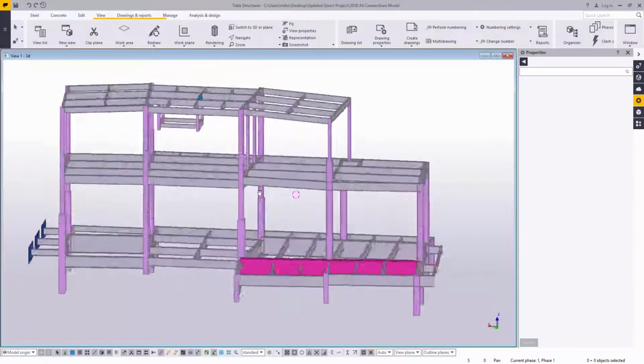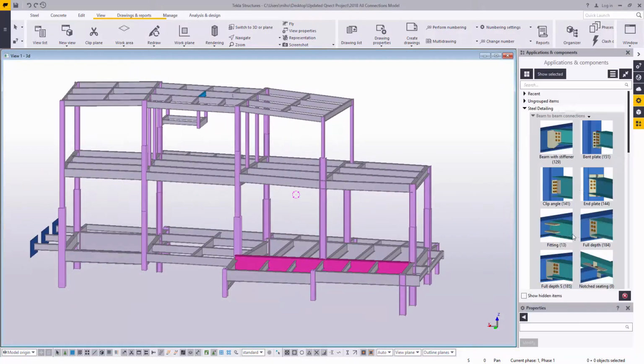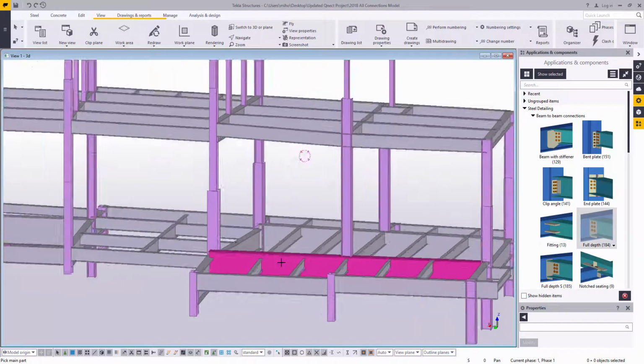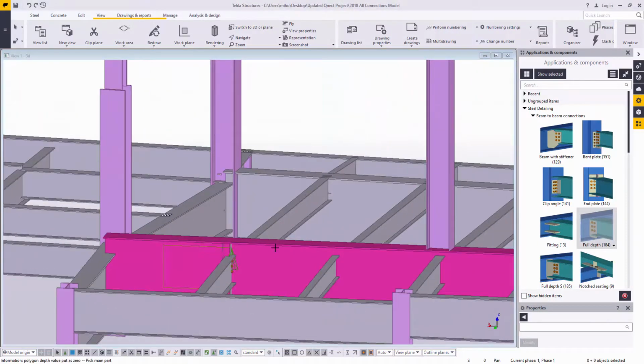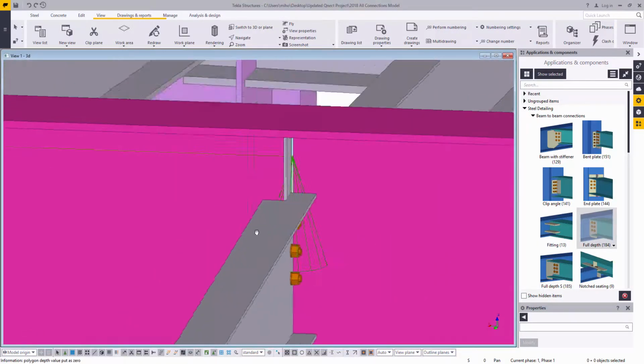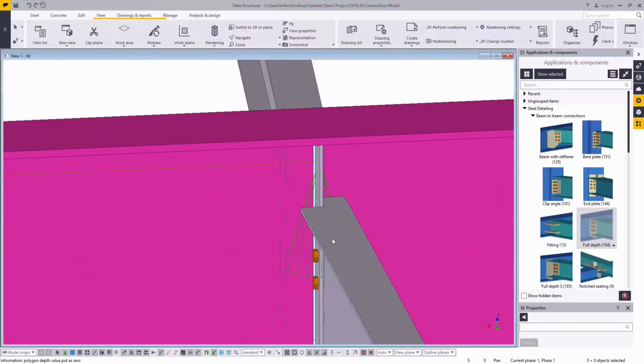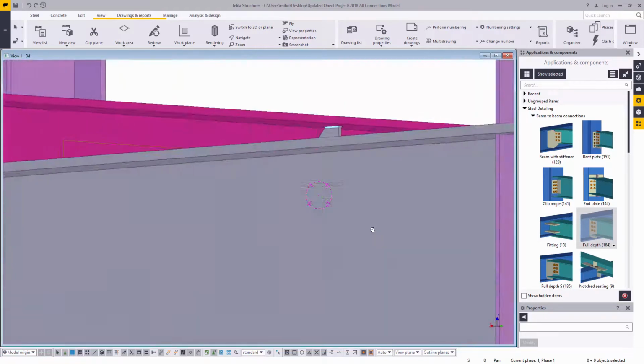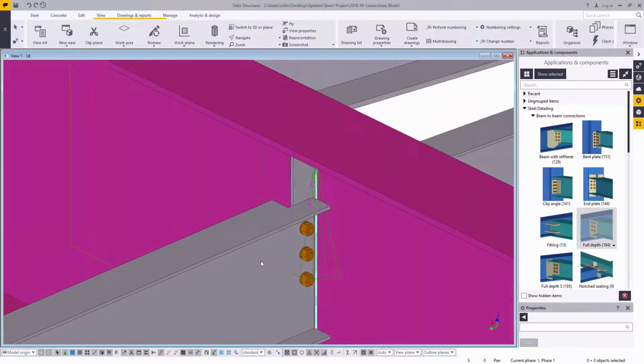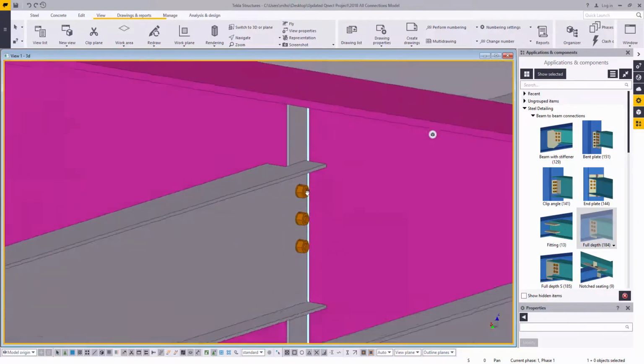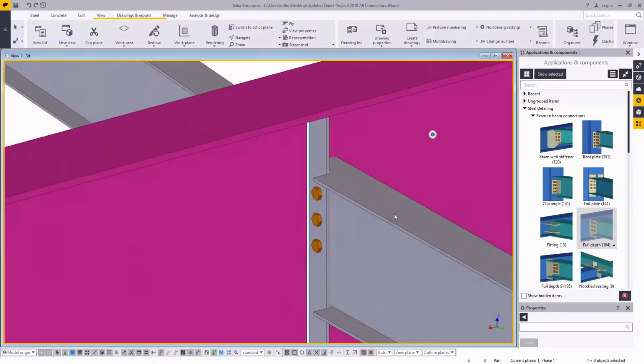Typically, to apply connections we have a library of components within Tekla, and we quite simply select the connection we want and drag and drop it into the model or by area. The connection then is set up to suit the engineers or detailers or fabricators standards by simply clicking on it and changing the parameters. Typical method of applying connections within Tekla.